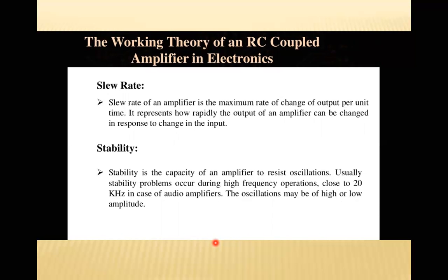Stability. Stability is the capacity of an amplifier to resist oscillations. Usually, stability problems occur during high frequency operations, close to 20 kilohertz in the case of audio amplifiers. The oscillations may be high or low in amplitude.